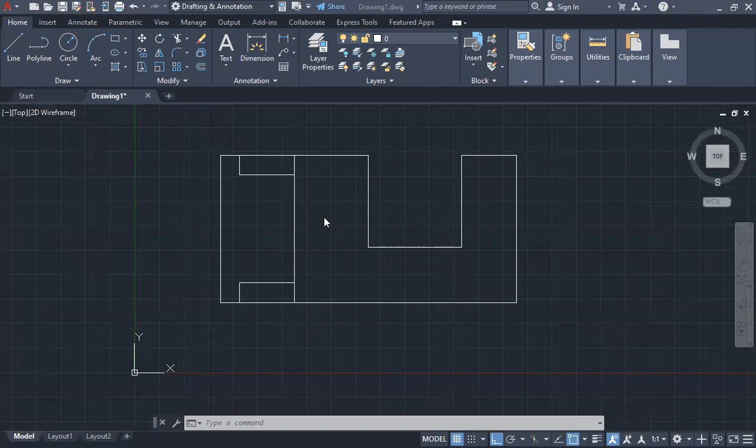After that, this midpoint line, I drew using my midpoint snapper. So I just started my line command, moved my mouse over this line until I hit the midpoint symbol. The midpoint symbol looks like a triangle. So that little triangle shows me my midpoint, and that's why I started my line and connected it down to this bottom baseline. And then I drew a short line from this point, the midpoint, across 28, down by 10, and then back to my midline, and did the same at the bottom. 28 across, 10 up, and then back to my baseline.